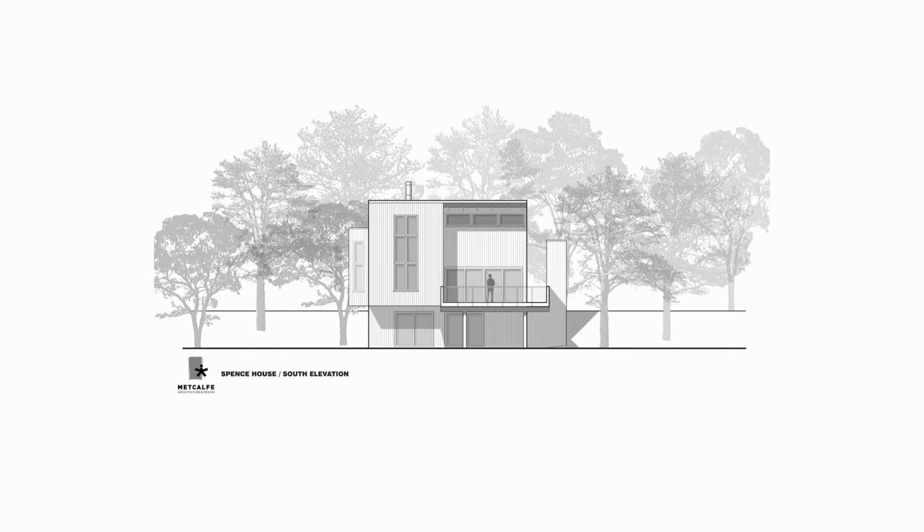So we move from the hand-drawn into some of the more computer-drawn. So there's going to be a mix today of AutoCAD elevations and Revit elevations in these. Obviously, we're not covering Revit in this class, but this still gives us a pretty good sense of line weights. As I've said before, using 5 line weights would be ideal on any drawing. If you get 5 line weights, your drawing's pretty good, generally speaking.